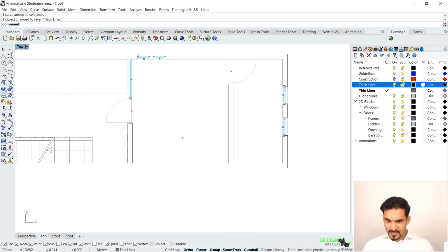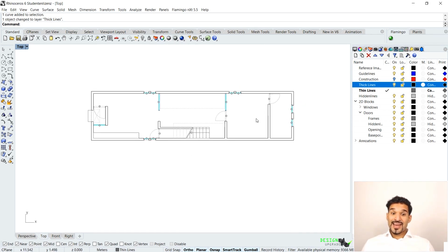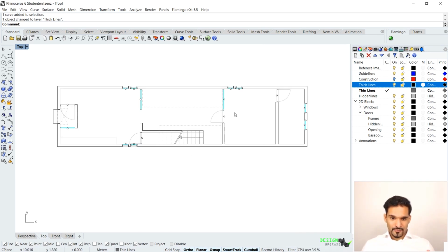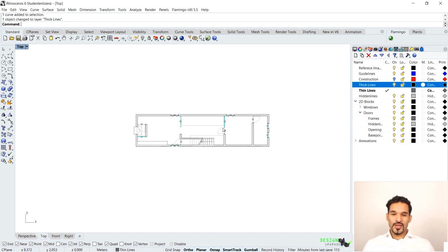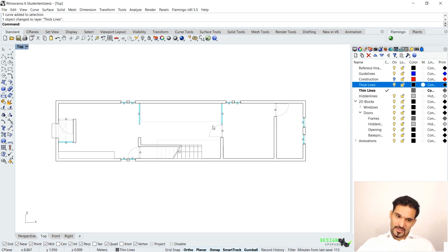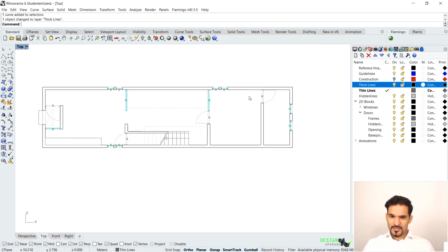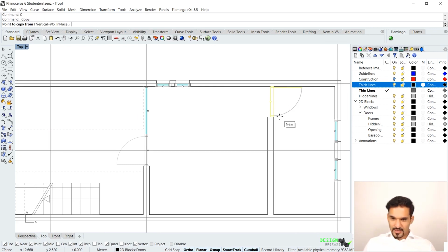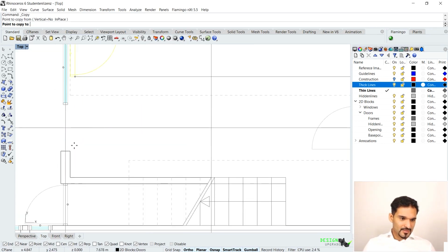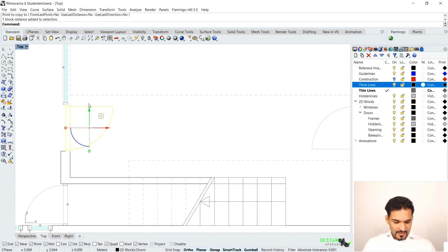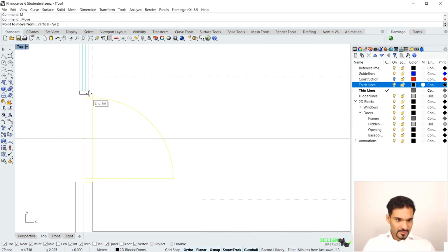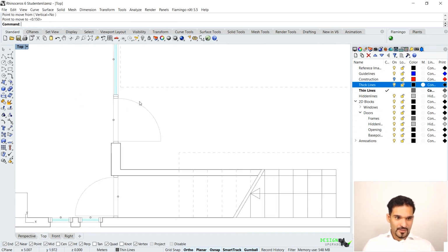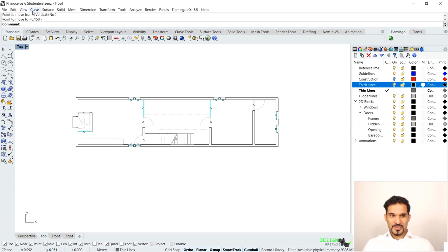Basically, the kitchen is placed here and the bathroom is here. Now we have a beautiful first floor plan. Congratulations. Now what we can do is actually continue on with the second level. Now you see what happened? Sorry, I just have to copy that. That just sometimes happens and it's super frustrating if you have just done it like me, not copying that. So I'm just gonna do that. Always copy your instances, otherwise you will have that.